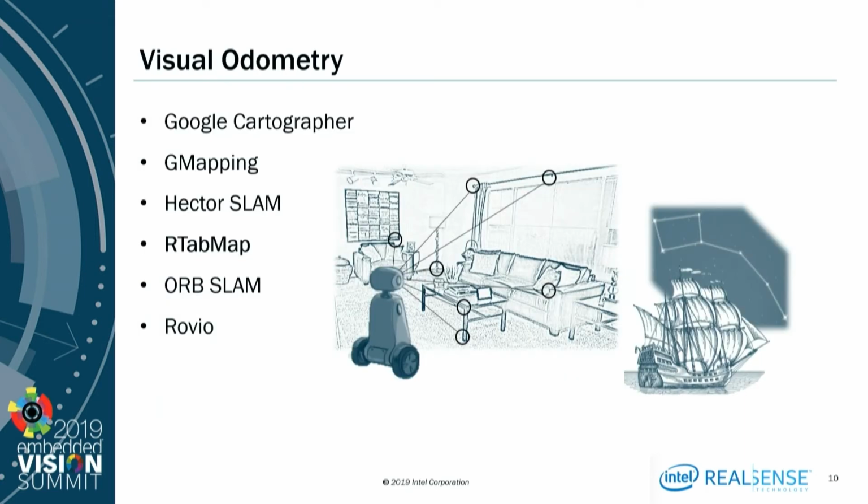The next component that we're going to require is a visual odometry system. A visual odometry, or VSLAM, is an algorithm designed to estimate the location and the orientation of the device in 3D space based on features in the environment, while at the same time updating and maintaining a map of these features as it goes. This is somewhat similar to the idea of navigating via the constellations, in that it relies on triangulation. And there are many free and commercial SLAM solutions available.